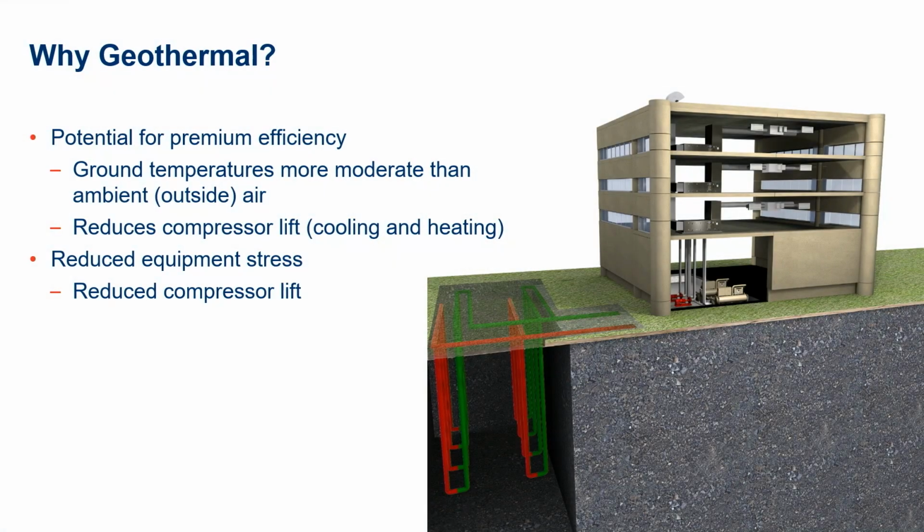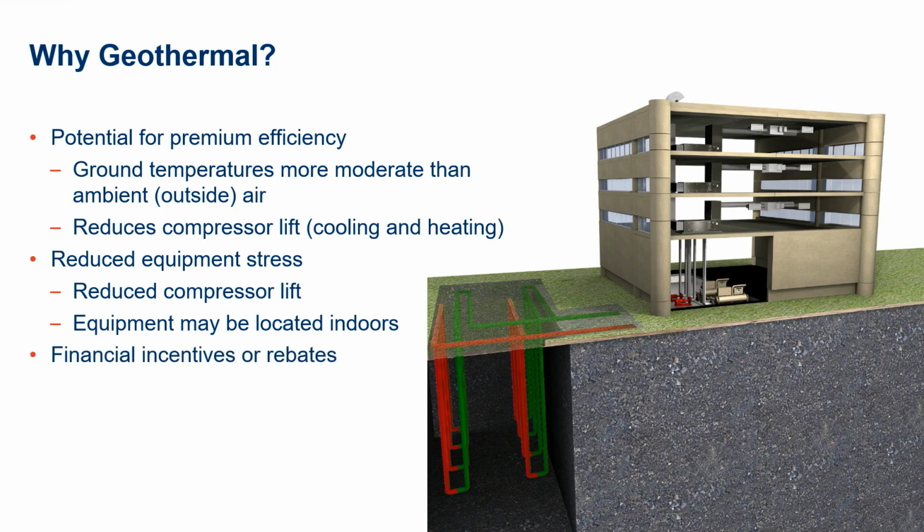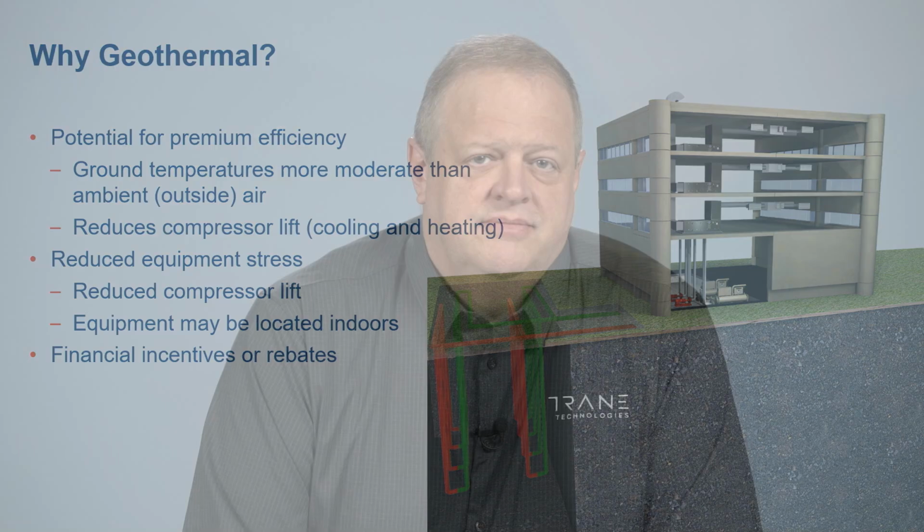Now, geothermal can also reduce stress on the HVAC equipment. Again, the reduced compressor lift means it doesn't need to work as hard. And the equipment can often be located indoors, protecting it from the harsh elements outside. Finally, geothermal may qualify for tax incentives or utility rebates.